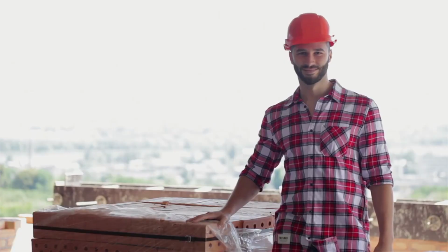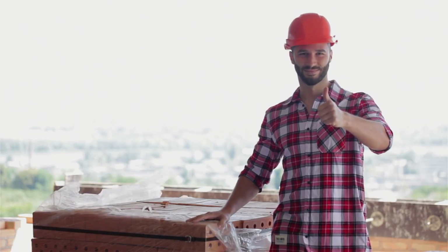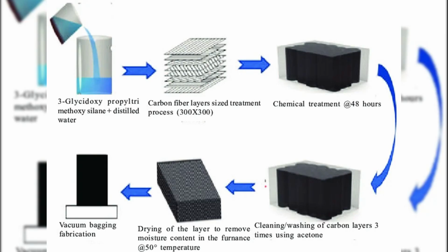However, at this stage, they are still not ready to be used in real engineering applications. The reason lies in the surface of the fibers. Freshly carbonized fibers have a relatively smooth and chemically inactive surface. This means that if they were directly combined with polymer resins, the bonding between the fiber and the resin would be weak. In composite materials, strong bonding between these two components is essential for transferring mechanical loads effectively.